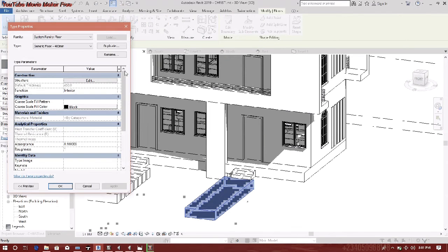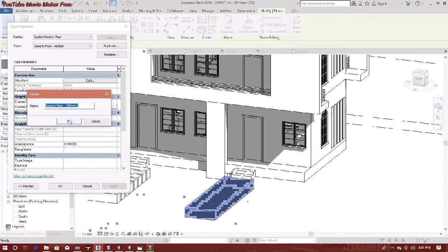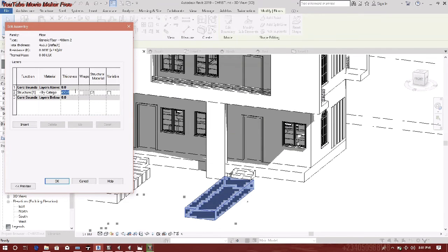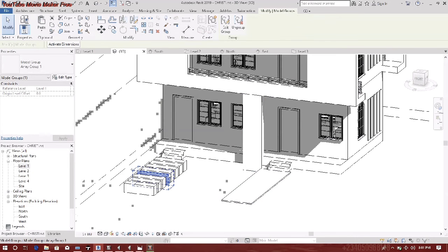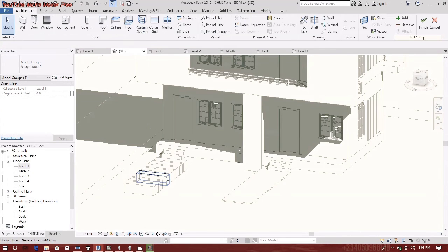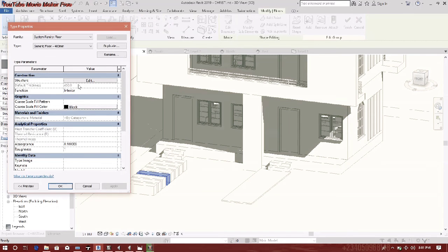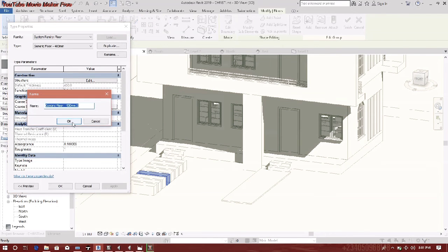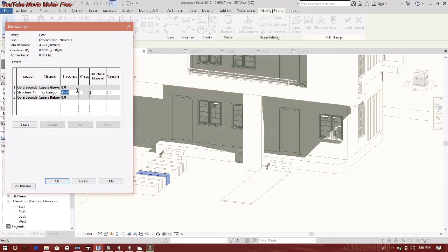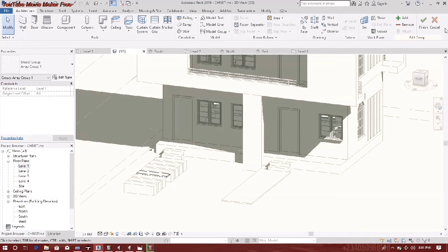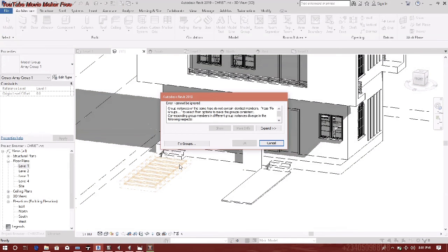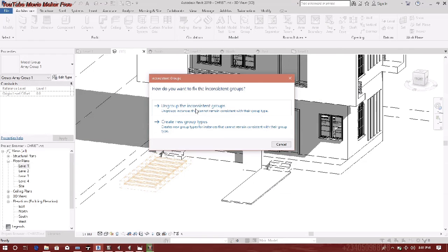You would come here, I spoke about that, duplicate first. When you duplicate, go to edit, then change this to something like 50, so it would not be on the ground directly. Then here, array. When you use array, you just need to edit one of it, then it will affect every other thing. Duplicate, then use 50. Okay, we could have used the same material that is here. When you click on finish, you see that it will apply to the rest. Fix group.